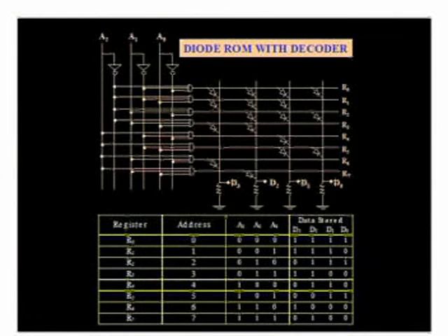Instead of using the switch select arrangements, we can use the decoder arrangements also. A decoder is nothing but something which will convert the active input signal into a corresponding coded output signal. Now let us see the figure. Here we are constructing the ROM using the decoder arrangements. In the decoder arrangements, we are replacing the switch select arrangements by decoder arrangements.